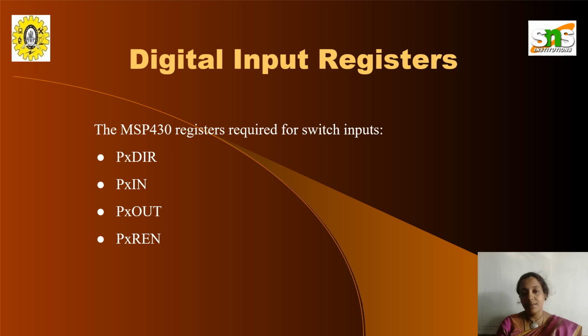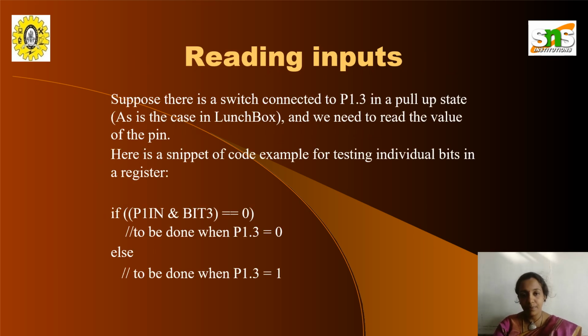Digital input resistors. The MSP430 registers required for switch inputs are PxDIR, PxIN, PxOUT, and PxREN. So, reading inputs. Suppose there is a switch connected to port 1.3 in a pull-up state and we need to read the value of the pin.